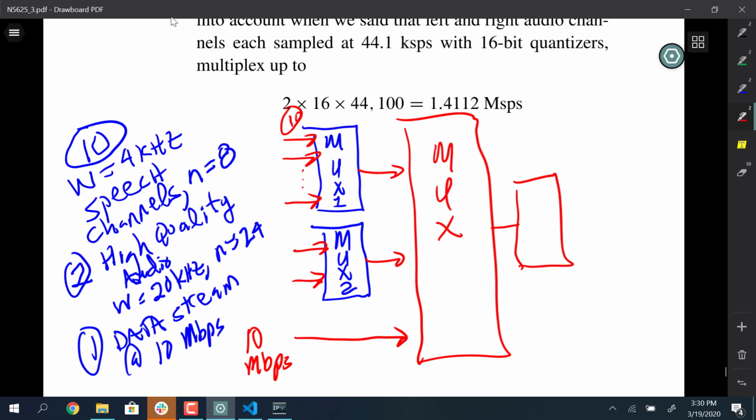How I'd look at this is different levels of multiplexing. So we'll multiplex the 10 analogs together, and those 10 analogs are each going to be at 64K, because we already did that calculation. We have 8 bits per sample. For Nyquist, we have to multiply 4 kilohertz by 2. So 2 times 4 times 8 is what that number was that we did before.